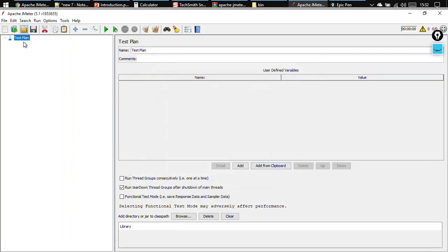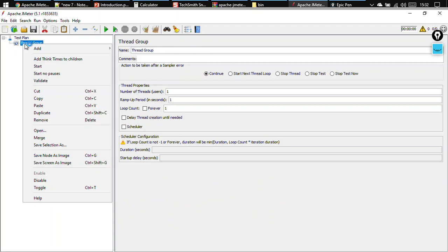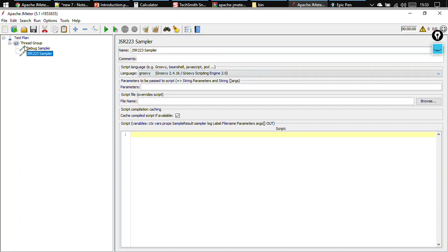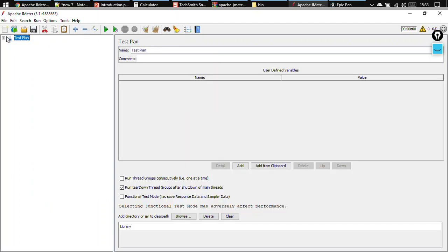Then there is cut, copy, paste. This is used for the elements you have highlighted on this Project Explorer pane. And the next thing is the plus and minus mark. This is used when you have multiple nested elements and you want to expand everything, or you just want to collapse everything. Suppose I'm adding some elements. Don't worry about the type of elements right now, I'm just adding some dummy elements. Suppose this is expanded. If I click this button, it would be collapsing everything. If I click this button, it would be expanding everything. I'm collapsing everything. If I expand it, you can see that there is only one thing getting expanded. If I click on this again, then it is expanding everything. So expand all and collapse all.